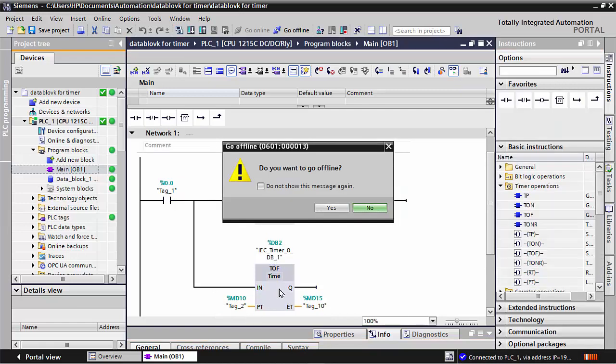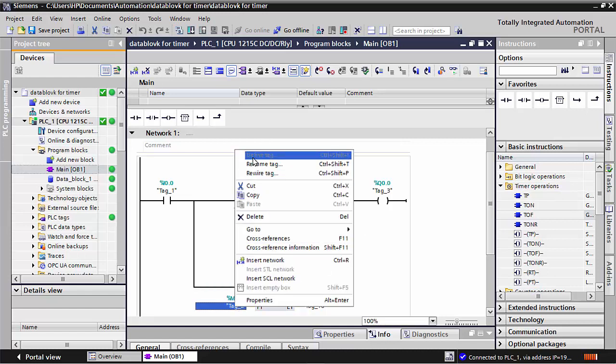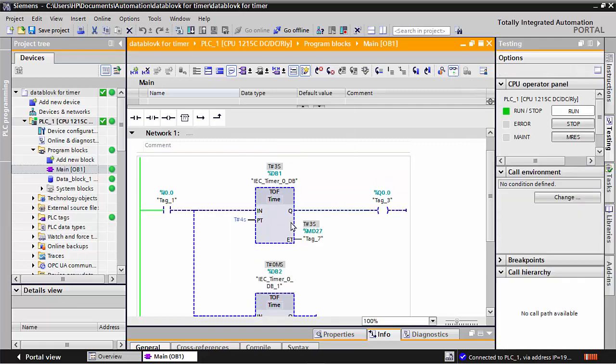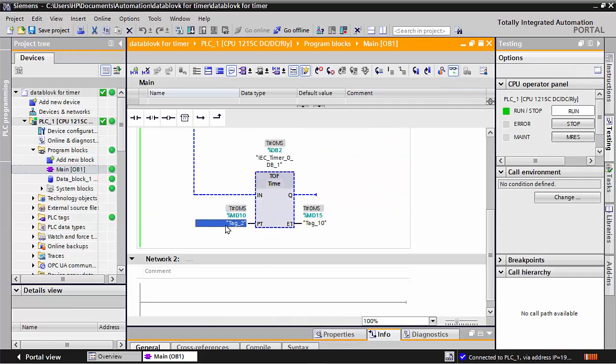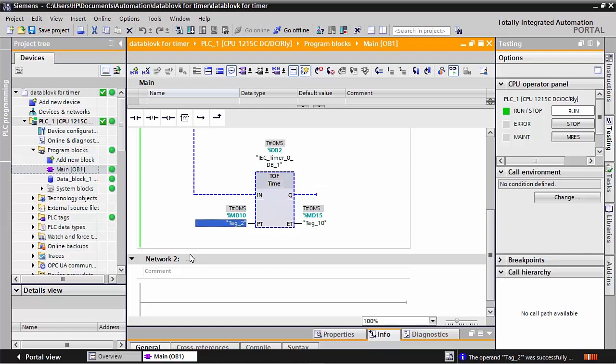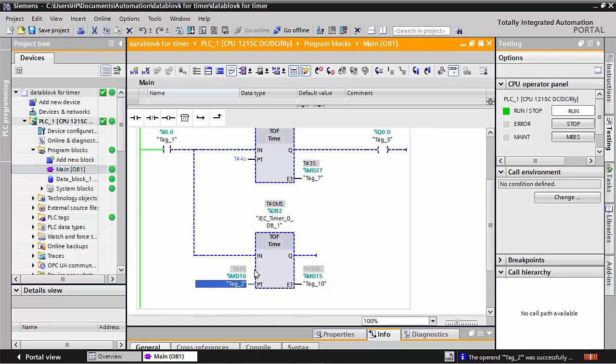You have to stop the simulation once, go to modify, and here you can give the time 3000 or I give 5000. 5000 is in milliseconds, so this is totally 5 seconds, but you should write it from HMI in decimal, you have to write 5000. After this it will count 5 seconds.